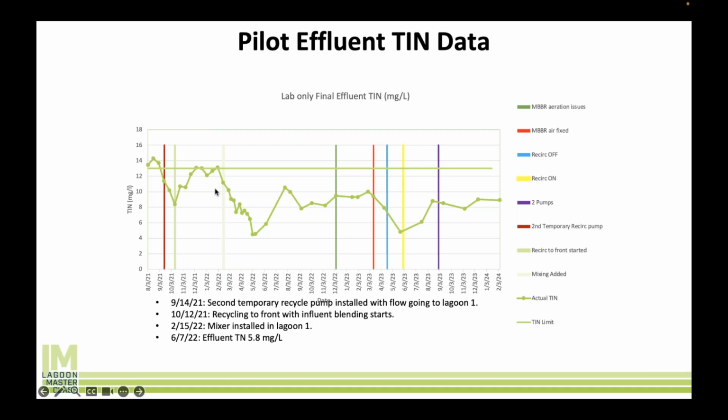And if you know anything about wastewater treatment, mixing is always a good thing, right? Mixing gets the food, the bug, and everything to mix together. And so that's where we plopped in our mixer, and we saw an amazing drop in the total inorganic nitrogen. So it really dropped down over the course of that year, and it's really stayed well under their 13 limit, and in a lot of cases under the 10 target that we had for this plant, despite some operational hiccups here and there that I won't go into.